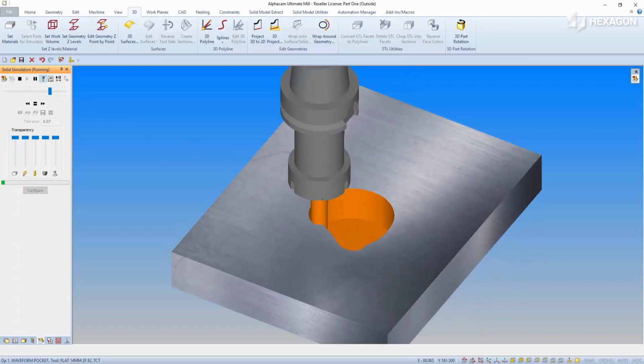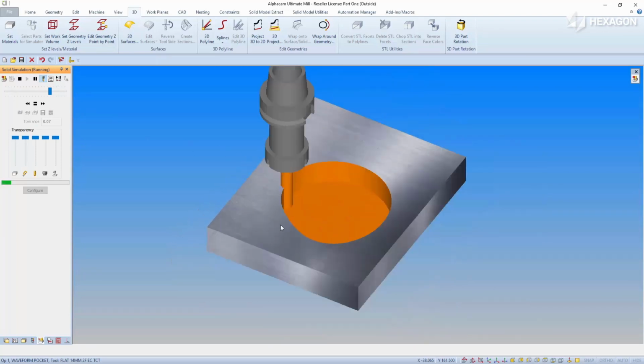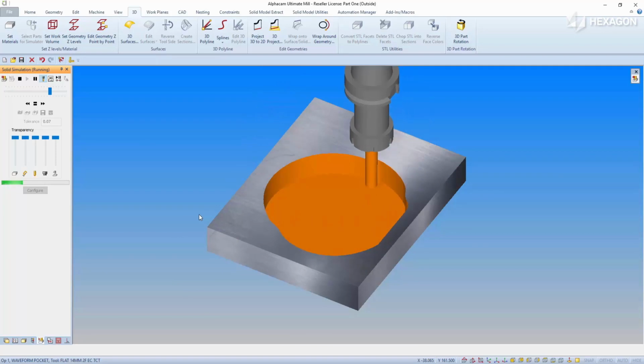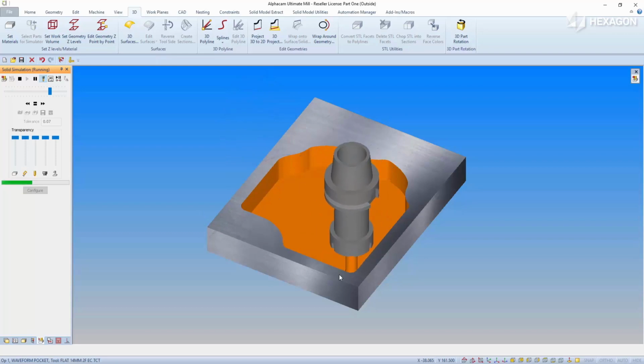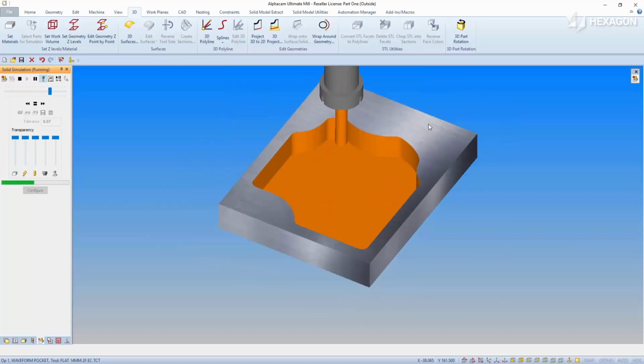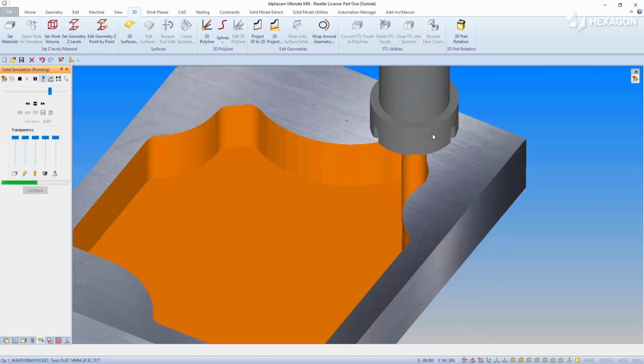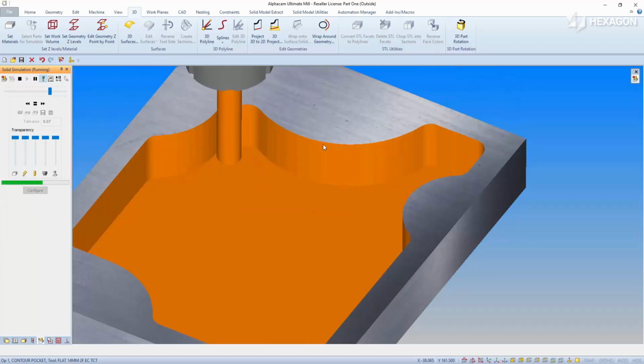Cutting along as much of the flute length as possible distributes wear evenly along the entire flute length, rather than just the tip. The radial cut depth is reduced to ensure consistent cutting force, allowing cut material to escape from the flutes. Tool life is further extended as the majority of the heat is removed in the chip.